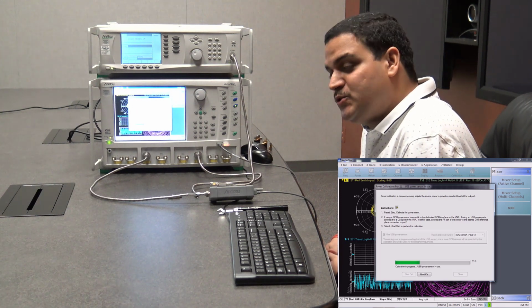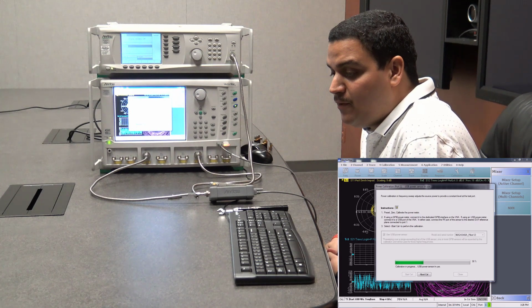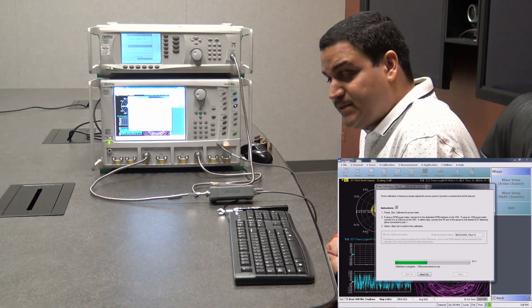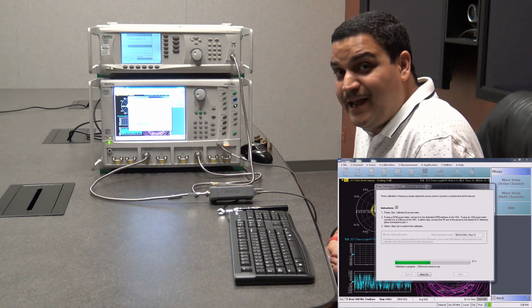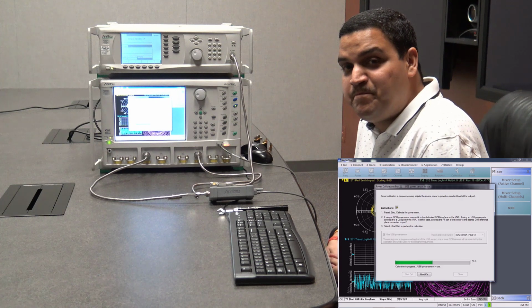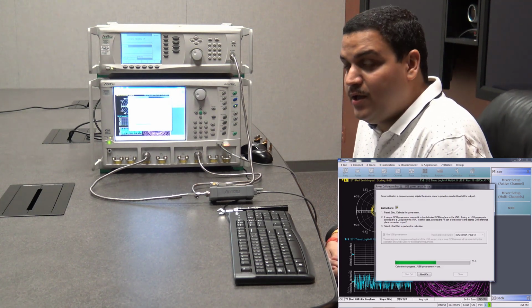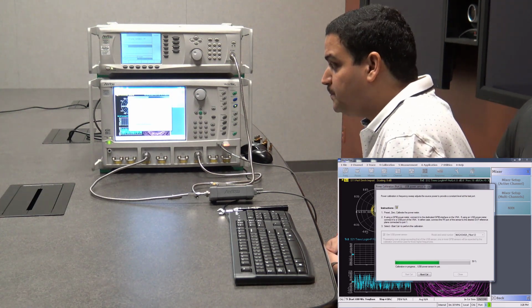For the actual DUT, we de-embed it from the measurement, and then we can get the group delays, etc. for the test mixer. If you are interested to see how the N by N or the reference mixer approach works on the vector network analyzer, please let us know, and we would love to have that video done as well.